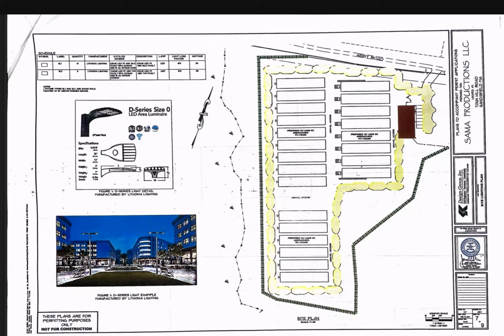Typically in this part of Massachusetts, there's a list of non-invasive street trees that are a part of any road construction. I looked at 3 other subdivision standards in 3 other towns. Take Lee, for example, which has a pretty good one. They want a street tree of a certain size about every 40 feet. So we show trees all along the frontage of the property, all planted at the interval consistent with if we were building a road. That's really the only place where there's an opportunity to provide any planting.